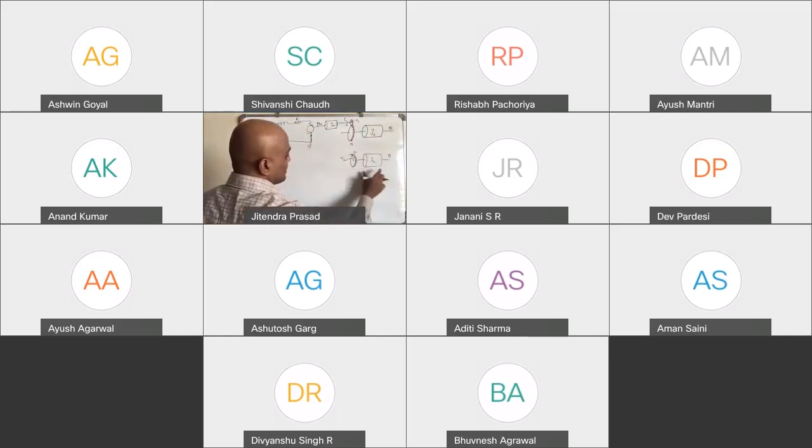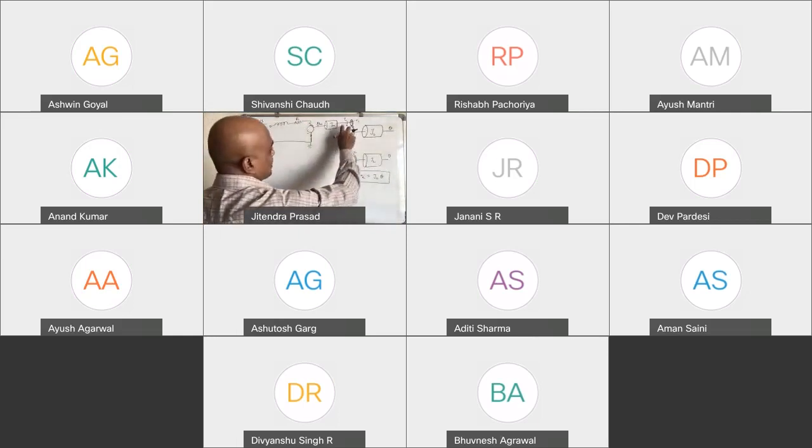Let's say for this one system, we have tau 2, which is equal to F times R2. This is the common force between the two gears. This will be given by JL theta double dot. So this we know, given the torque and how the theta is related with this one, right? So this equation we have to use. Now look at this one.